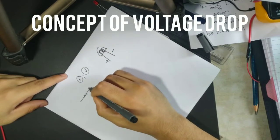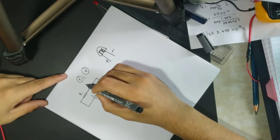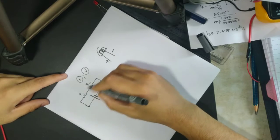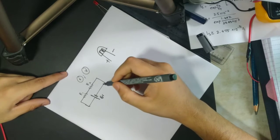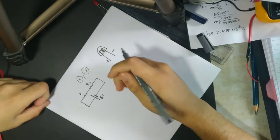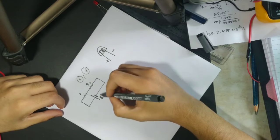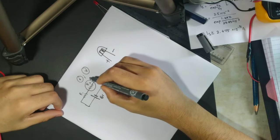Suppose we have two resistances and a battery, say the resistances R1 and R2. For example, the potential difference which I apply between these two points is, say, 6 volts. So what will be the voltage drop across these two? When I say voltage drop, I use the word drop because you have to imagine that this resistance would eat up some of the voltage which is going through it. Of the 6 volts, suppose this resistance is very hungry, it will take in, say, 5 volts.